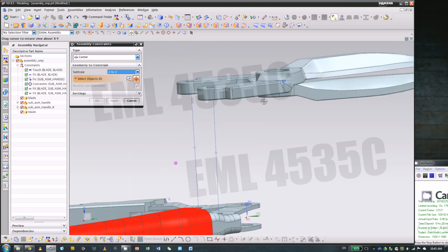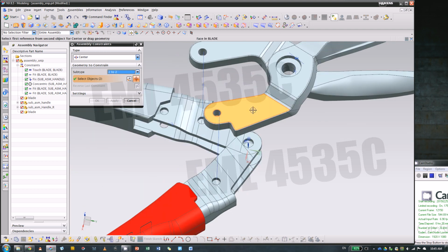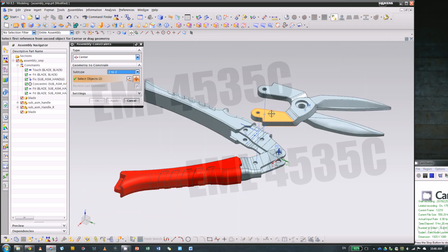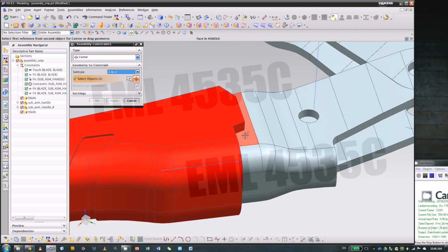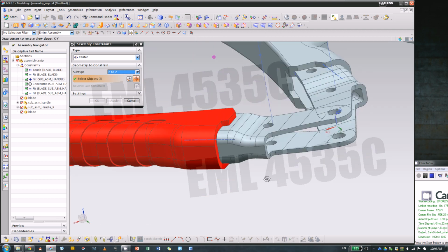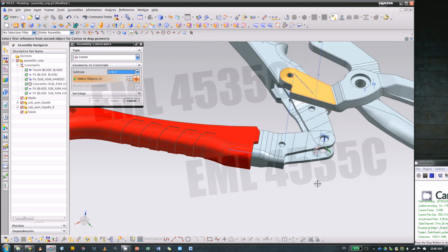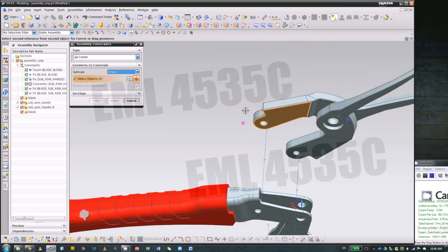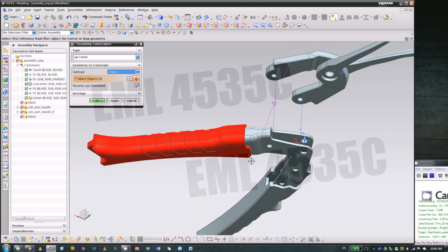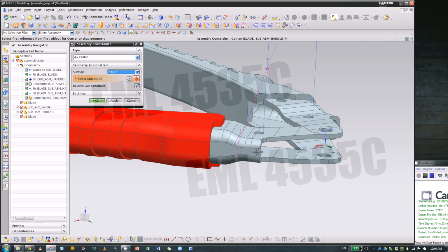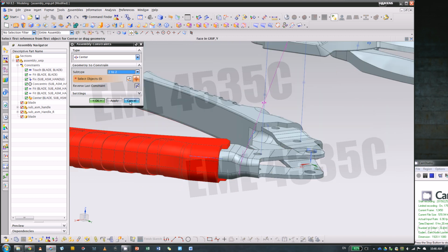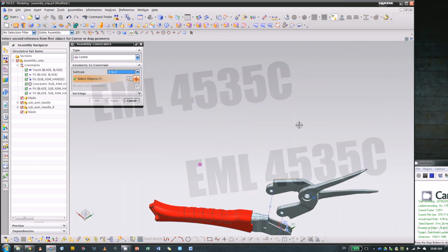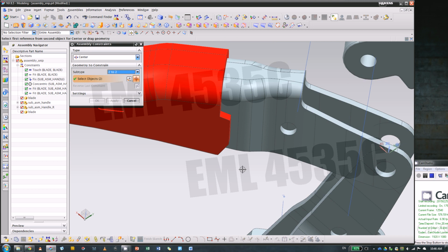We have this top and bottom surfaces. Once you click those two surfaces, it'll automatically find the center of those two surfaces to be centered to probably this face. And usually for the pair of faces, I will pick parallel faces. I've never tried non-parallel faces, or maybe they never work well. And as you can see, it doesn't work well with non-parallel faces. So I'll go back and pick parallel faces. That is the first pair. Second pair is this one.